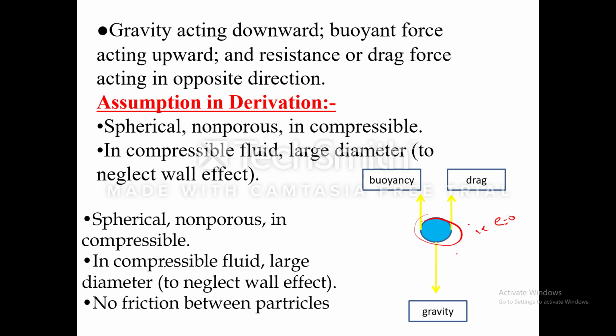So we will see that the gravity force takes the particles down, and the drag and buoyancy forces take the particle upward. So if Fg is larger than Fb and Fd, then the particle will settle. If not, the particle will still hold constant.